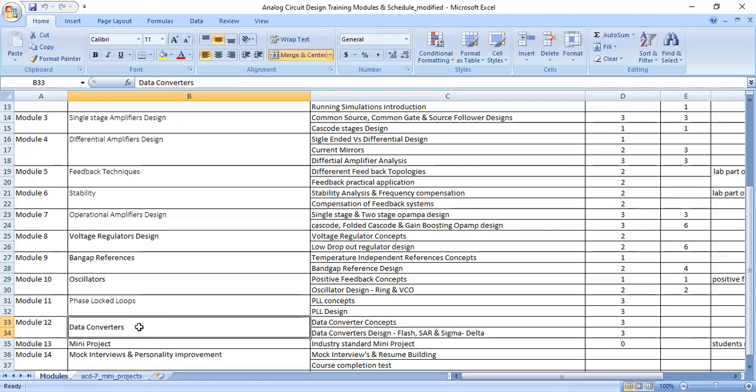The main tool we are using here is Cadence Virtuoso as a design tool, where we can launch ADE, ADXL. Along with that, in ADXL, we can do the different simulations, as I mentioned, like AC, DC, transient, whatever you want, and analyze the results. The basic technology that we are using here is two technologies: TSMC 65 nanometer and GPDK 90 nanometer.